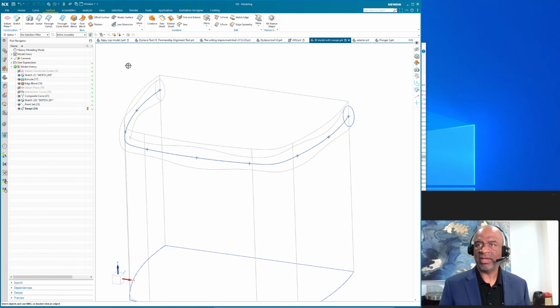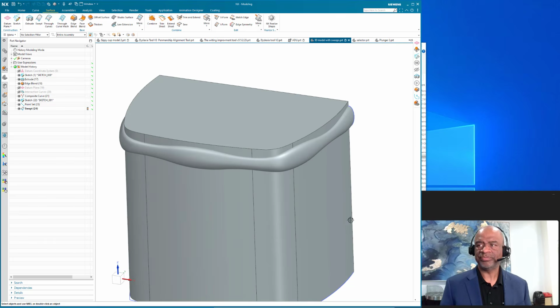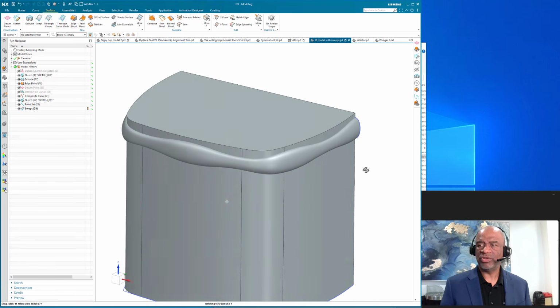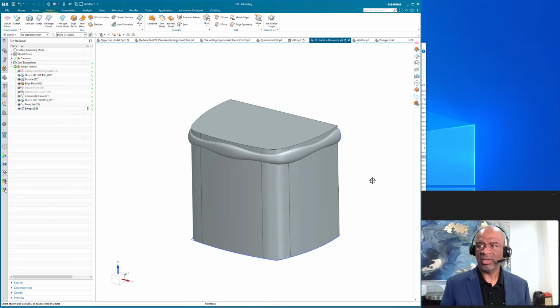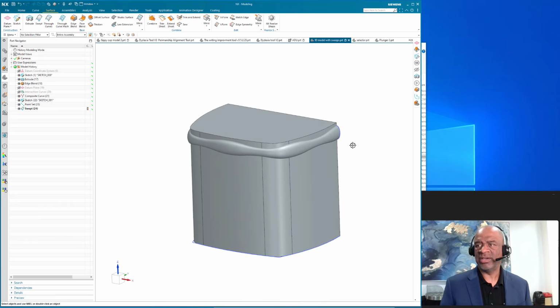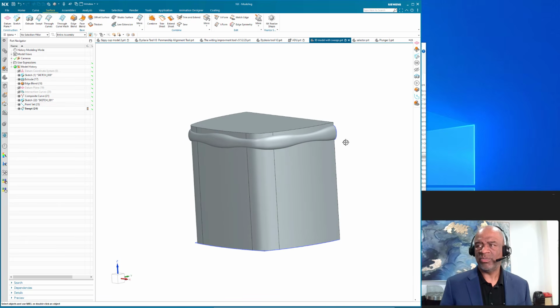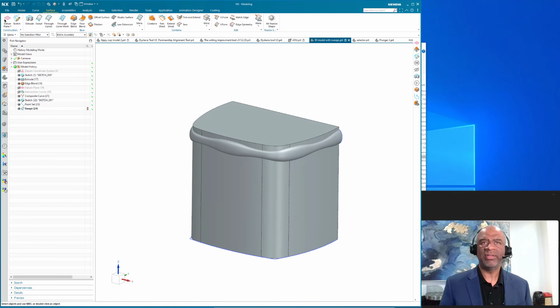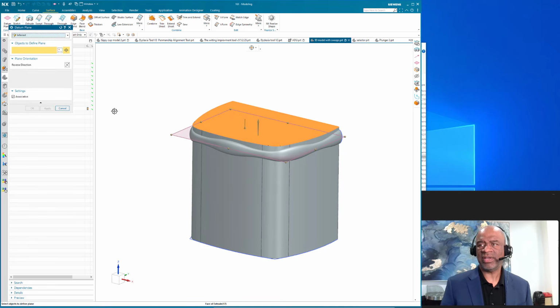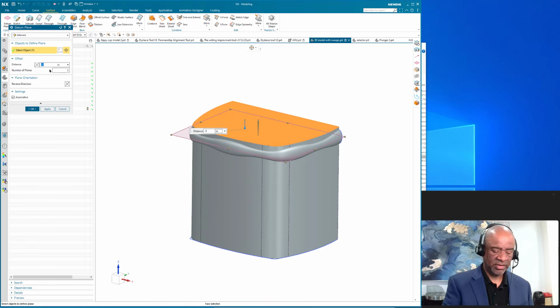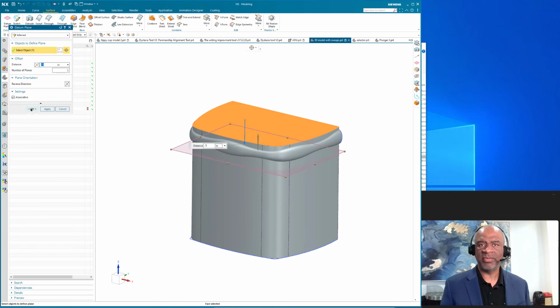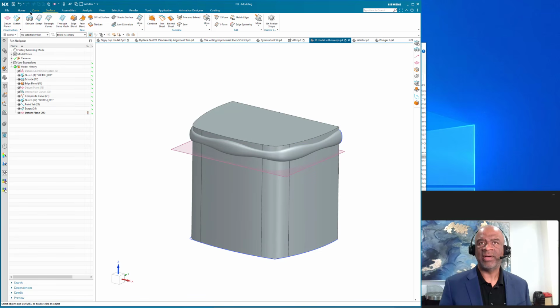Now you have this piece of geometry. This geometry I'm going to use as a cutter. But I need another corresponding geometry that will be small, big, small, big, small, big. So I'm going to put another datum plane here. And this datum plane is going to be offset by minus 5. It'll be apparent why in just a moment. Minus 5.